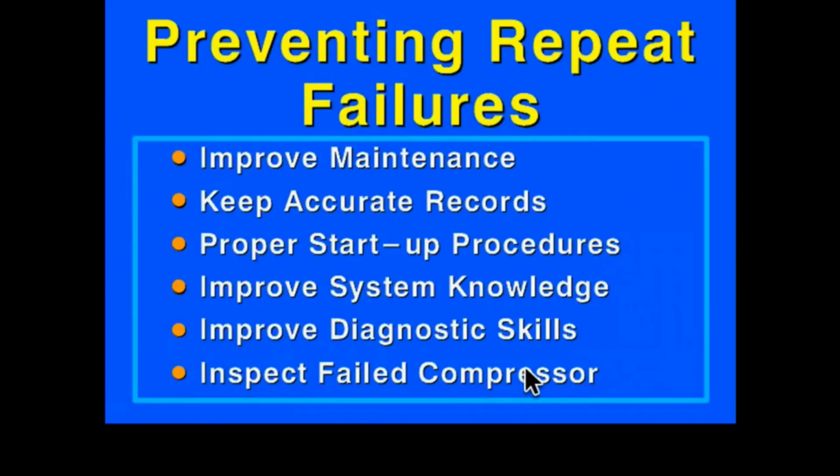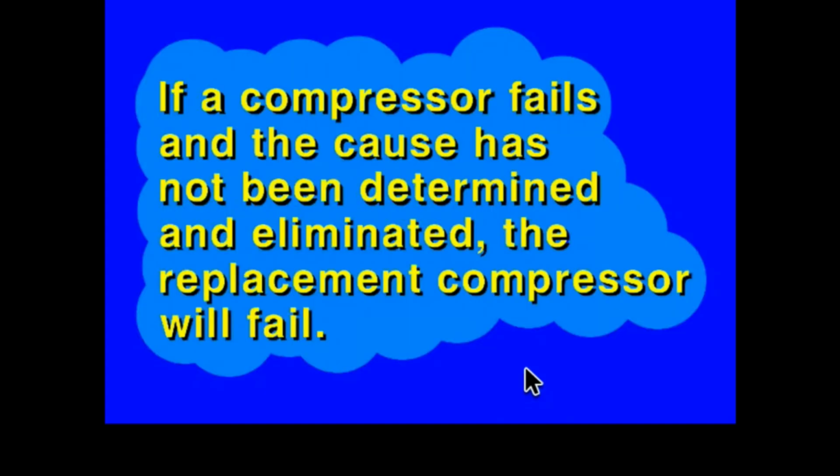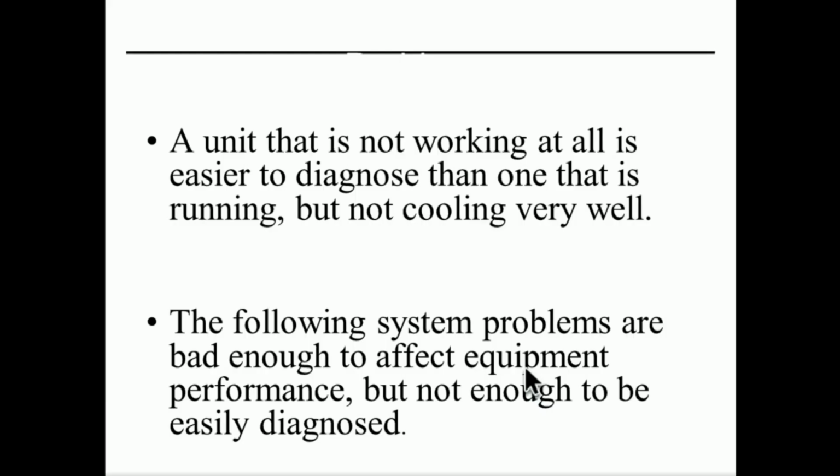Basically, maintenance and keeping accurate records, proper start-up, system knowledge, then diagnosis, then inspect the failing compressor, because it's going to give you more information about the real cause of the failure. If a compressor fails and the cause is not determined and eliminated, the compressor is bound to fail again and nobody can stop it. Let's see now.